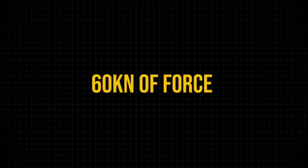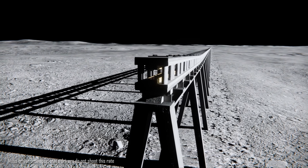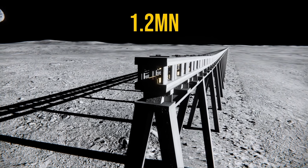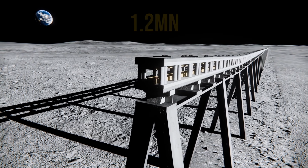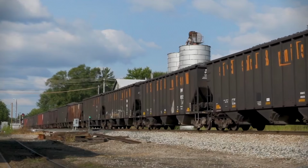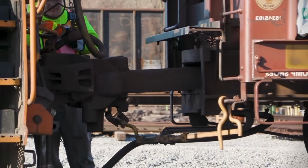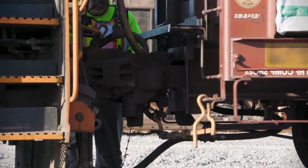But if that payload is moving at even just 2 kilometers per second and we try to curve it upward through a 1 kilometer radius bend, the payload pushes downward into the guideway with about 1.2 meganewtons of force. That is equivalent to the weight of about 120 metric tons on Earth, roughly the weight of a fully loaded heavy freight rail car, coming from a 300 kilogram payload.